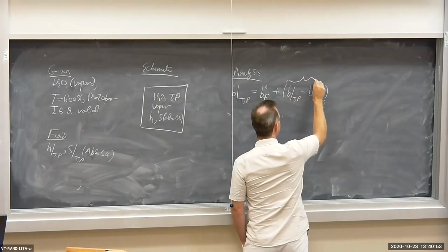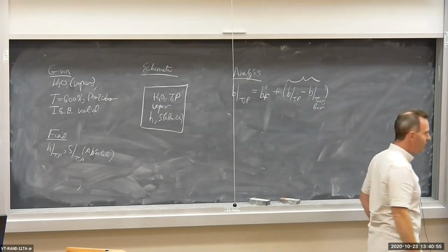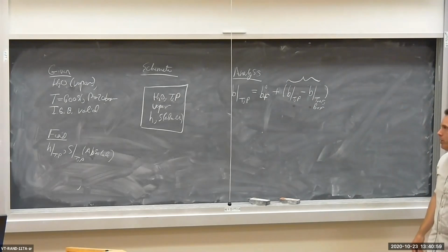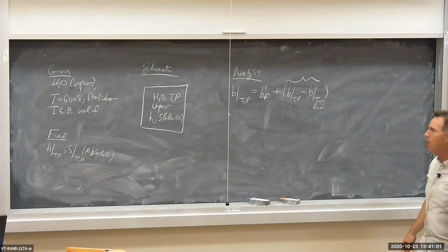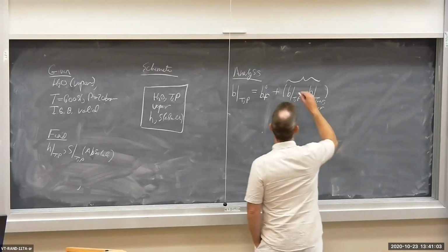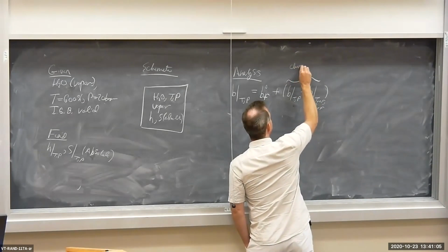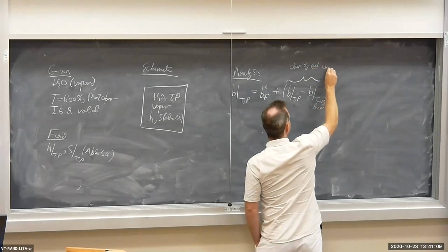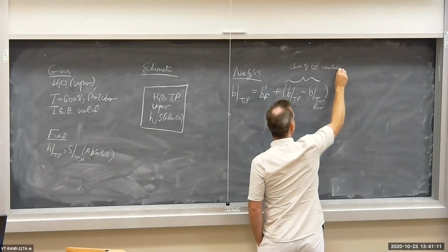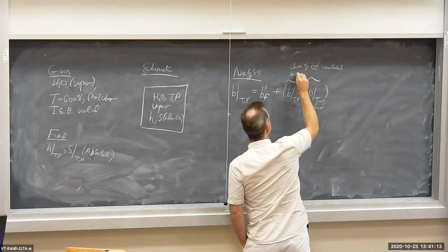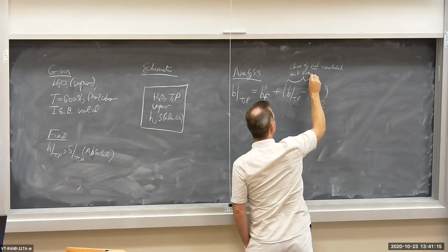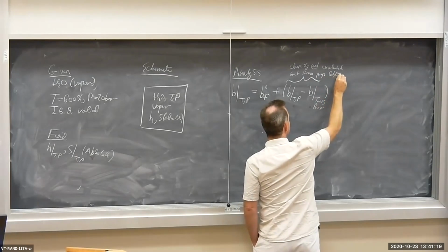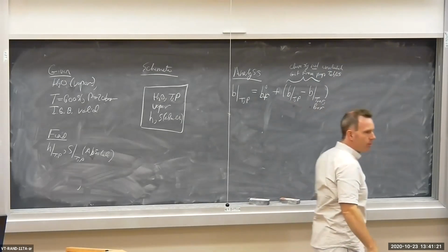And remember here, the betas in this difference need not include the effects of the chemistry. So we can get these from any property tables. Chemistry not included, get from property tables, okay?